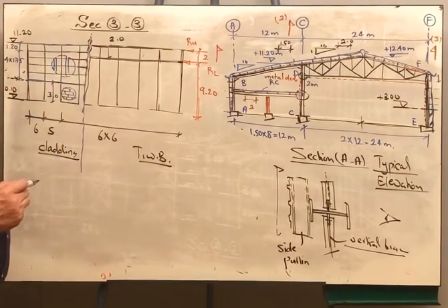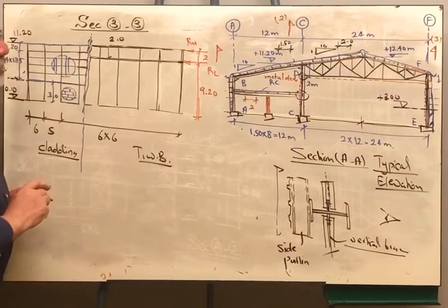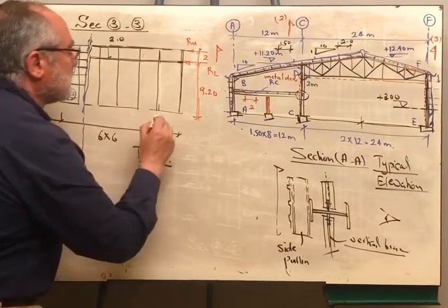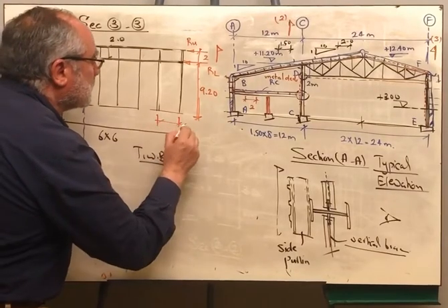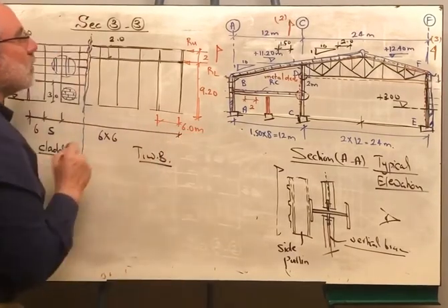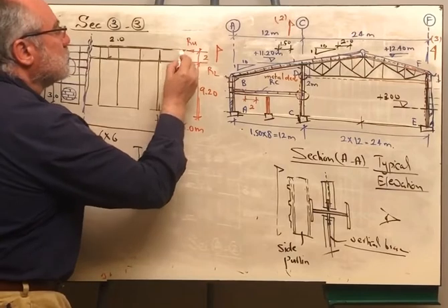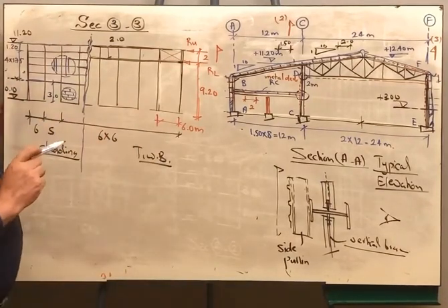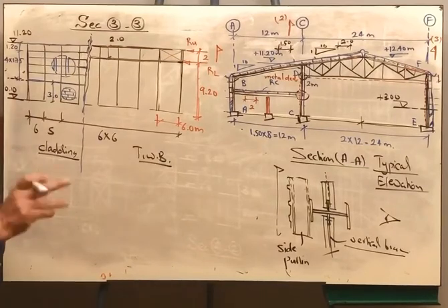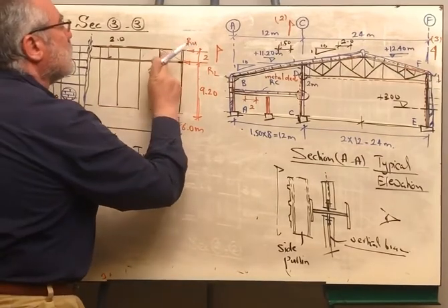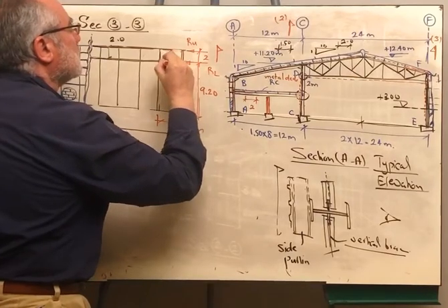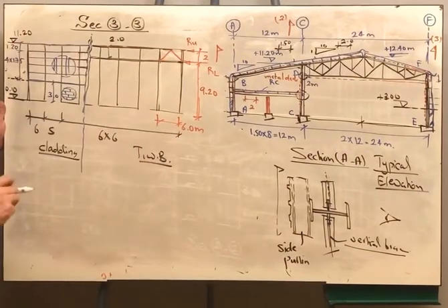Okay. Well, let us arrange the bracing. Again, this distance is 6 meters. Okay, so this is 6 and this is 2. If you take a cross like this, the angle will be very bad. It should be from 30 to 60. Therefore, I am going to use a K-truss. The K-truss is better.